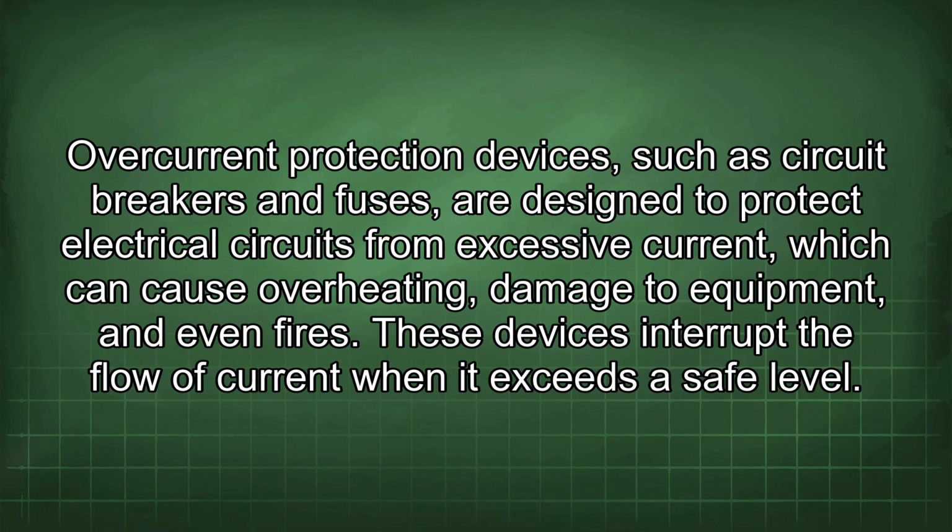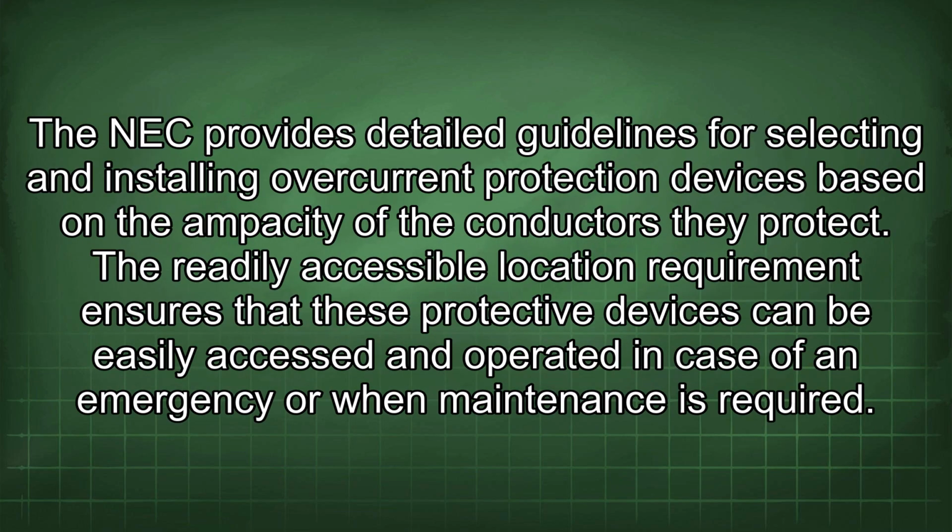Overcurrent protection devices such as circuit breakers and fuses are designed to protect electrical circuits from excessive current, which can cause overheating, damage to equipment, and even fires. These devices interrupt the flow of current when it exceeds a safe level. The NEC provides detailed guidelines for selecting and installing overcurrent protection devices based on the ampacity of the conductors they protect. The readily accessible location requirement ensures that these protective devices can be easily accessed and operated in case of an emergency or when maintenance is required.